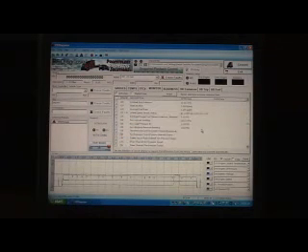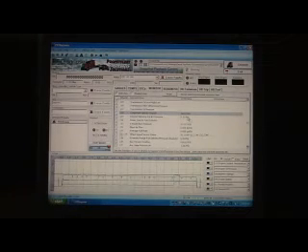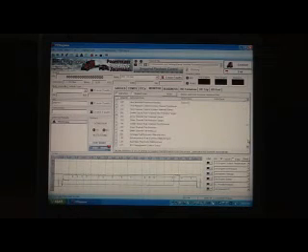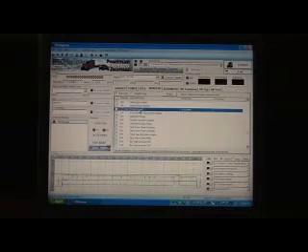If you wish to view a PID larger for ease of viewing, for example, if you're sitting in the cab of the truck and the diagnostic PC is out on your toolbox, you may wish to enlarge the view. To do that, select the PID, double click, and then a box will appear.